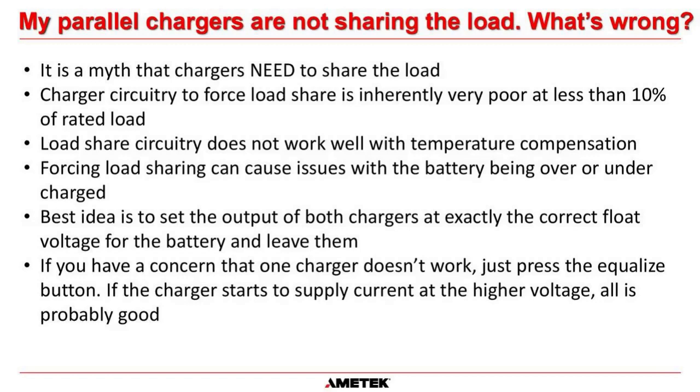Also, if you have a charger that has temperature compensation, then the load share circuitry does not work well with that, because one battery may be warmer than the other battery, and that causes issues. And then forcing load share can cause issues with the battery being over or undercharged, just because of the volt drop in the cables that I mentioned before.